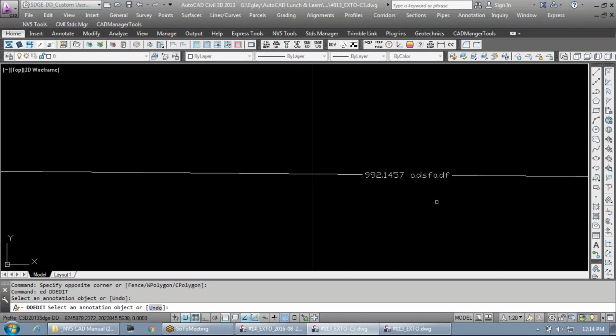By default, if you use the template, your drawing is going to be in California, but it's going to be zone 6, right? Because that's where this office is located. If you're doing work outside of zone 6, be sure to change your zone. You know, the gas group, we're doing a lot of work in zone 5. If you're working outside of zone 6, be sure to change your zone, all right?